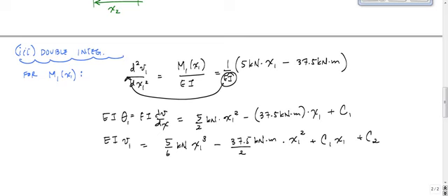And the units might look weird to you. You have this kilonewton meter squared, but what you have to remember is that EI comes out and is divided by. And the units of EI, we'll just calculate real fast. EI is equal to, in this problem, 200 GPa, which is really just kilonewton per millimeter squared, times 120 times 10 to the 6 millimeters to the 4th.